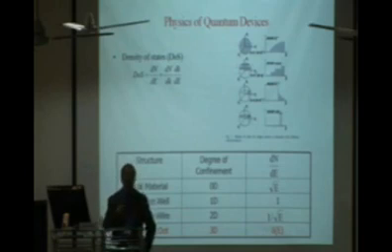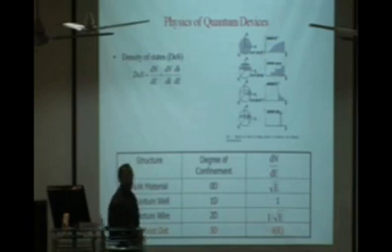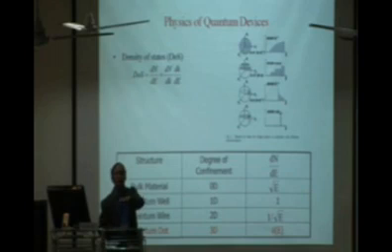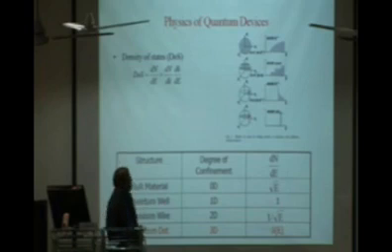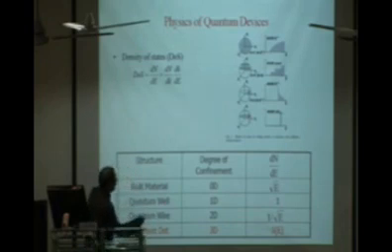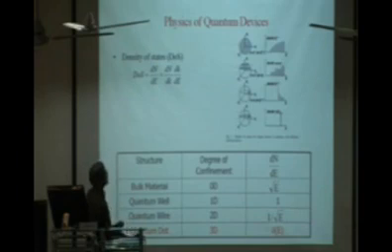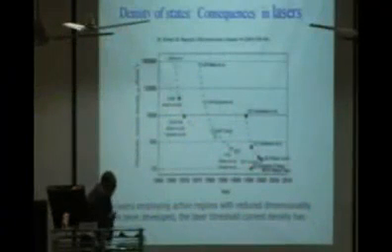Just like the lasers we get from atomic states, ideally, if you can really make quantum dots with the same monodispersed size and distribution, the density of states is very sharp. But practically it is impossible to make the dots in exactly the same size, so there is always broadening here. That's why this is one of the most preferred systems to make this kind of quantum devices.